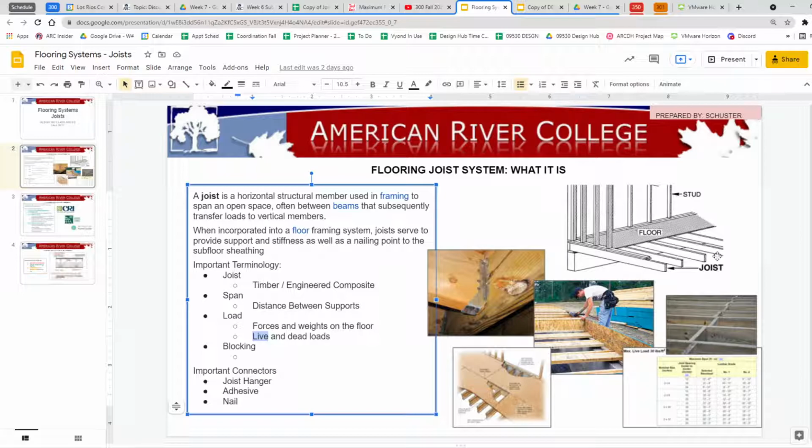Okay. Now, there are some standards that say if you design with this live load, you're pretty much going to be okay. Unless, for example, you put in a water bed. Water beds are extremely heavy. Or you put in a 1-ton fire safe in one spot. Or if you know that there's a big piece of equipment that's going to vibrate, like an air conditioner or something. So in general, your live loads are sort of estimated on what's reasonable and normal. And you can look those up in these tables.